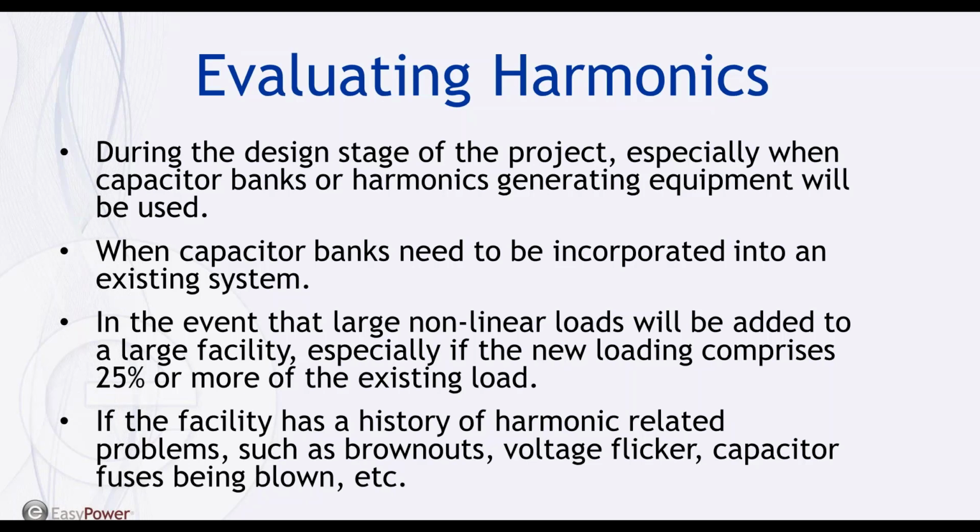It is recommended that a harmonics analysis and power system modeling be performed in the event that large nonlinear loads will be added to a large facility, especially if the new loading comprises 25% or more of the existing load. If the facility has a history of harmonic-related problems, such as brownouts, voltage flicker, capacitor fuses being blown, or some of the other things I previously mentioned, an evaluation should definitely be considered.